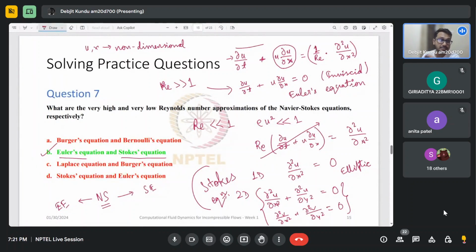And non-dimensional analysis is an absolutely crucial tool which can help you here. Instead of looking at different numbers, whether velocity is large or density is low or viscosity is large, you club them together into a Reynolds number and only look at that.